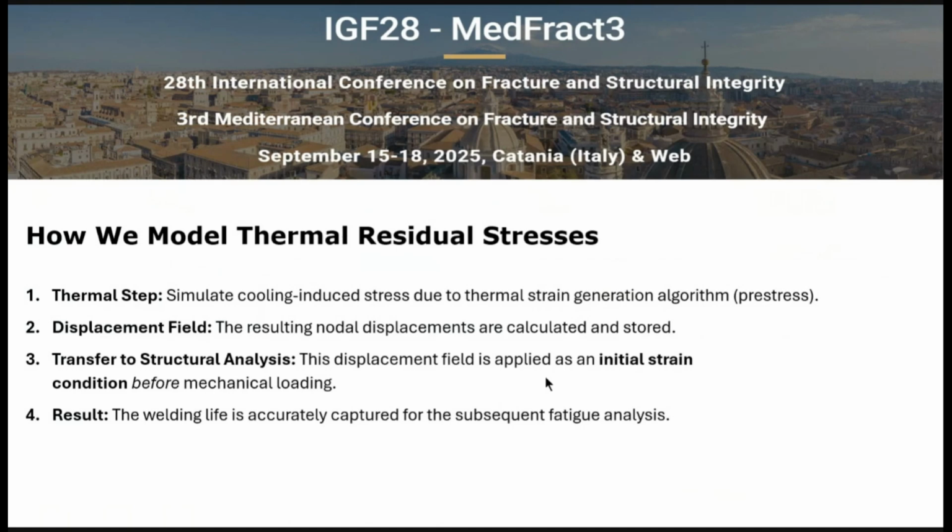After that, we apply this thermal stress as a displacement, transfer it to structural analysis, and apply the fatigue loading in static structural analysis. The results accurately capture the fatigue test results from experiments in the literature.